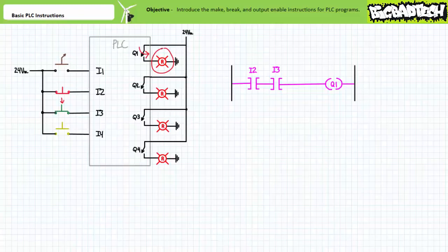Note, as presently implemented, this PLC program does not maintain the last asserted state, and due to the momentary nature of the field input devices, the pilot light attached to output Q1 only comes on when the green push button attached to input 3 is actively being held closed. As soon as the operator releases the green push button, output Q1 is de-energized and the pilot lamp goes off. While this might be suitable for some applications, we'll examine holding circuits that maintain the last asserted state as implemented in PLCs using virtual relays and their associated instructions, software-generated holding circuits, and latching instructions in later lectures.